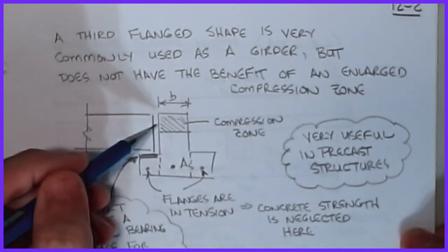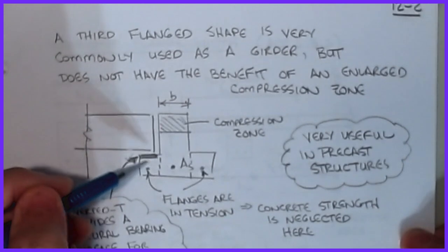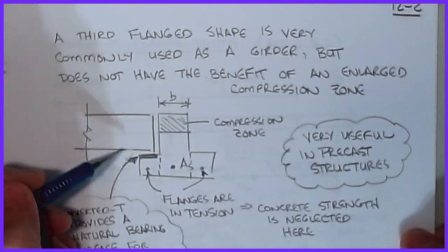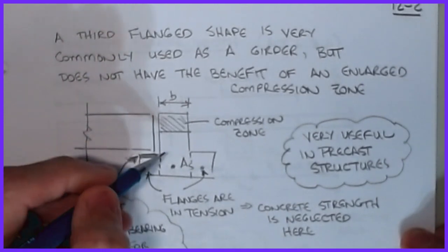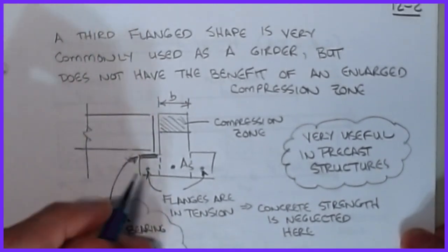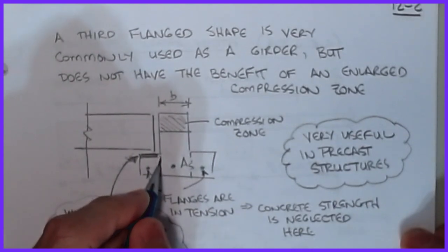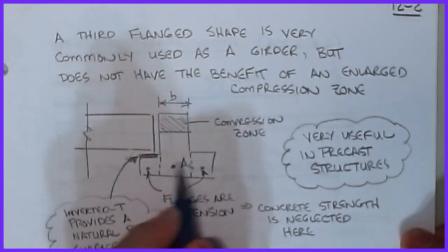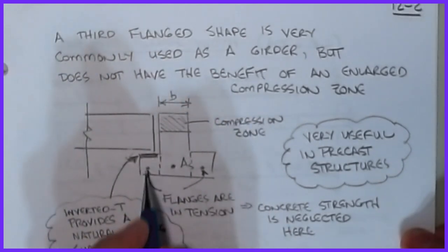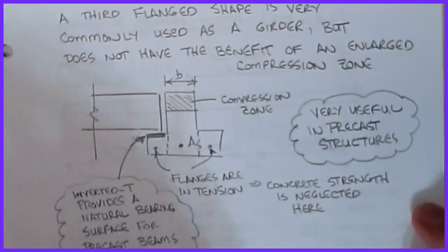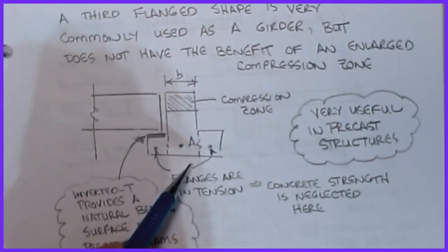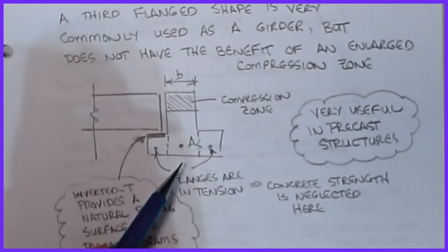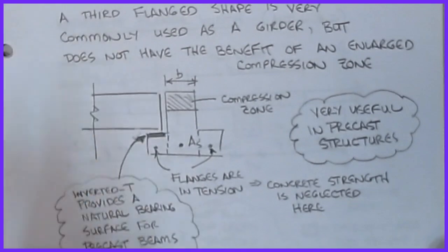If you go take a look at one of those, they almost always have an inverted T-beam running between the columns, and then whatever section, the double T's or whatever they're using in the parking garage, will just bear right here, and you can have a metal plate or some sort of neoprene pad or something that helps with the stresses. Now there are some design considerations that we're not going to address in this, in which I would more than likely develop tension at that corner, which means I would have to have some sort of reinforcement across here to help produce this haunch or this corbel landing happening here. But these are pretty common in practice. Now maybe not so much in the RC field, but definitely in precast or pre-stressed applications. They're very, very useful for those.